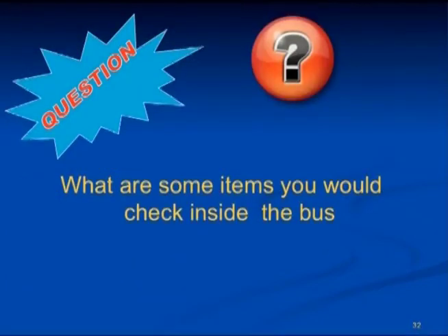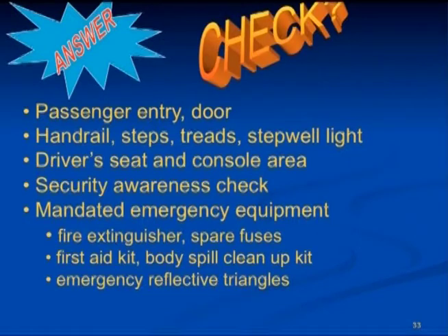What are some of the items on the bus that you would check inside the bus? Check the passenger entry door to include the handrail, steps, treads, and step well light. Check the driver's seat and the console area. Do a security awareness check prior to entering the bus. Use a flashlight if need be.